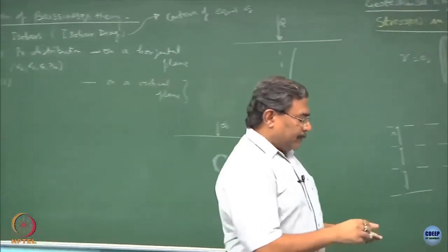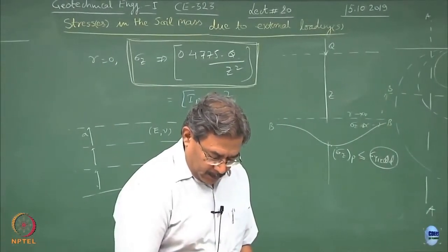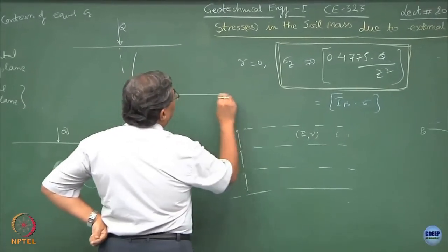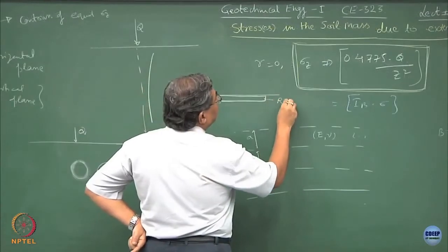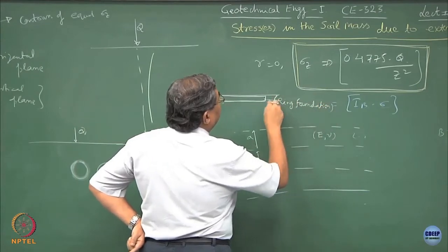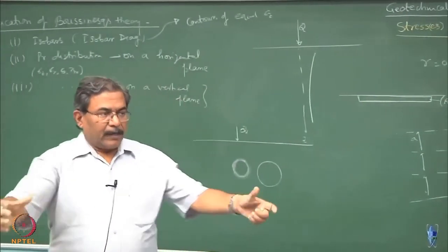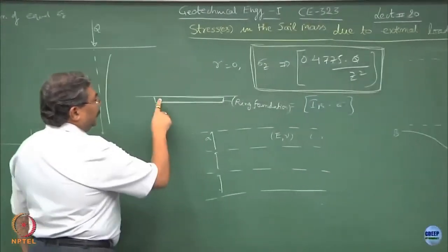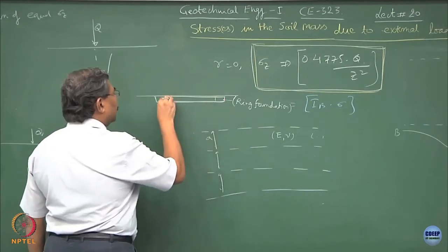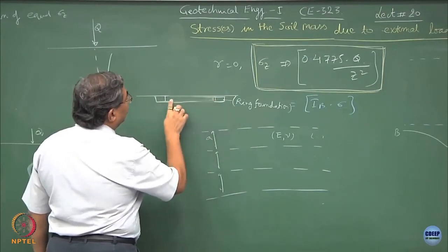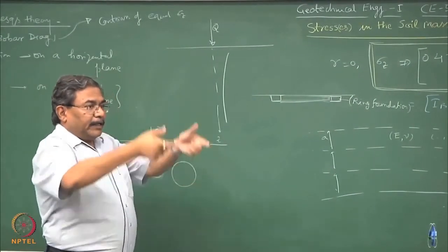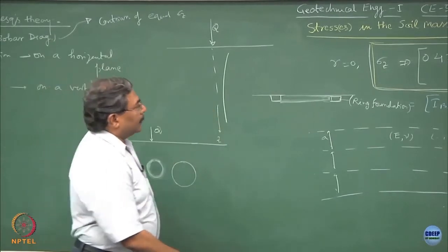But suppose I am designing a tank foundation, which you must be seeing, big tank farms in your structure. So, this becomes a ring foundation. Normally the oil tanks are seated on the ring foundation. I need not spend so much money because rafts are going to be expensive. What I will do is I will cut them into a ring. Is this okay? So, as if a ring is bearing the entire load of the tank.